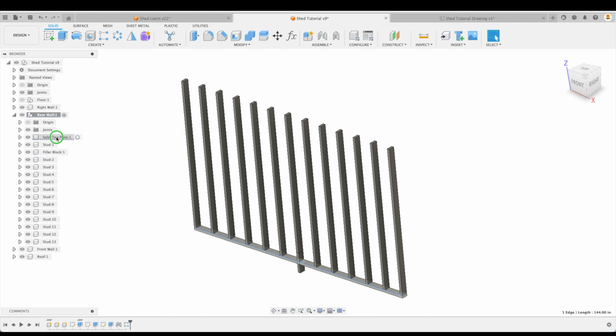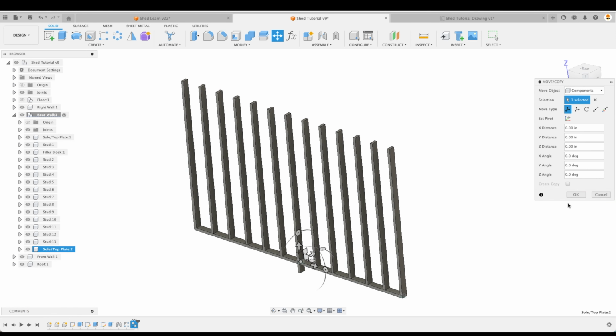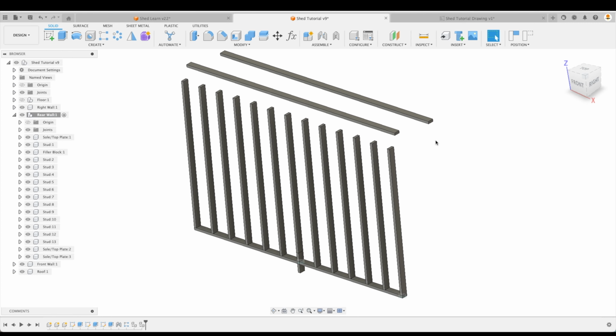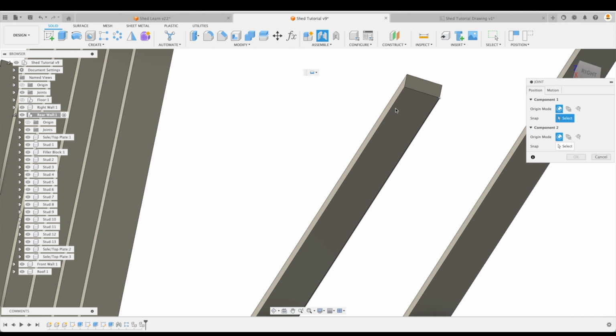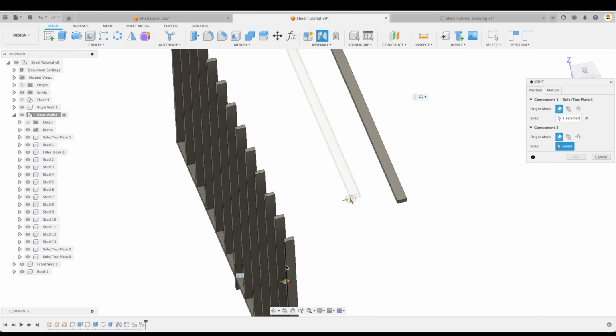So we can just click on that and right click copy. Now the shortcut, Command or Control V. Go OK, do it again. We're going to add 2. Now just select 1 and you can see it turns up in blue. Now we can drag it to the top, select the next one, drag it to the top, and there we have it. So here we can take these guys and we can assemble them to our wall.